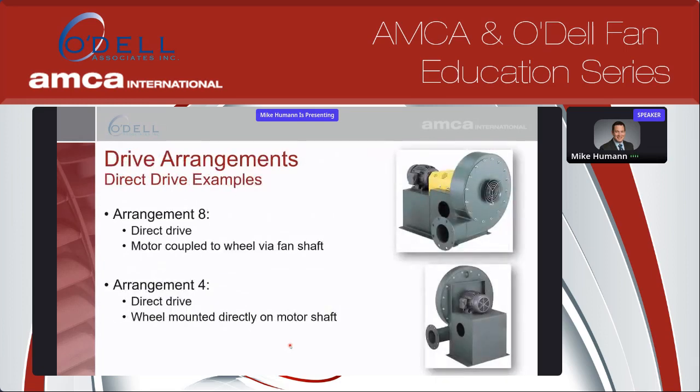So we talk about drive arrangements. The first arrangement we'll look at are direct drive fans. You see here on the right-hand side of the screen some examples of fans. The top picture is an arrangement 8 fan. You can see that the motor is coupled directly through a coupling into the fan shaft, and you'll have a set of bearings for the fan shaft, and then the impeller will ride directly on that fan shaft or kind of jack shaft.